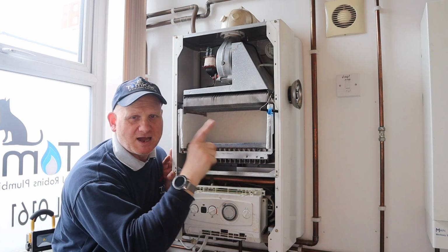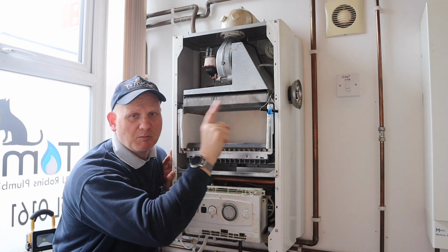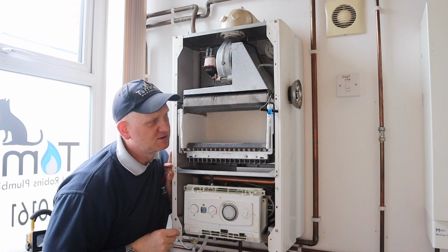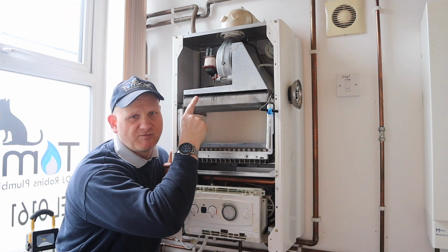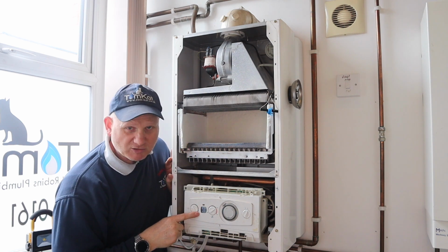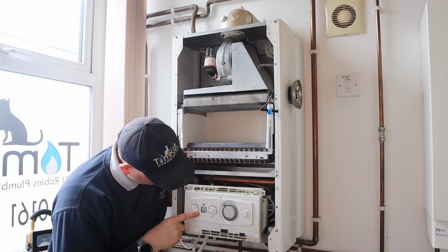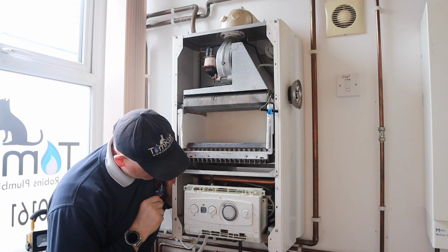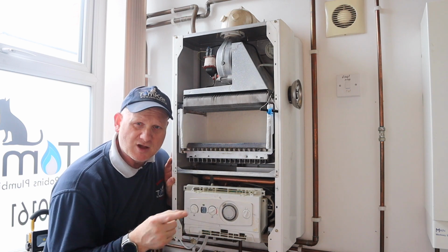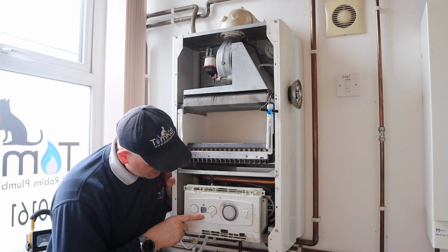So it basically knows I've bodged it and tried to bypass the air pressure switch. So it's not even brought the fan on. And it's not put a fault code up yet. It's still saying 23 degrees on the front. So it knows it's calling for heat because it's gone from the pressure to the temperature.